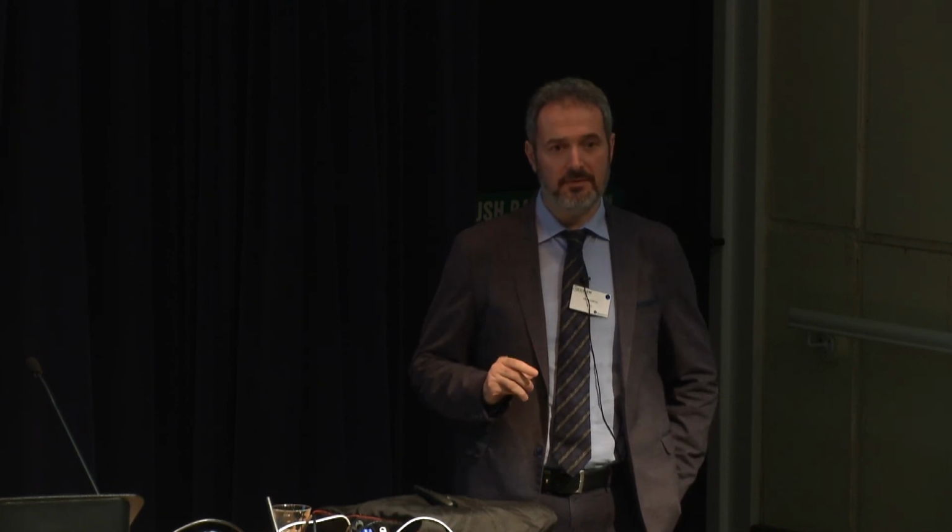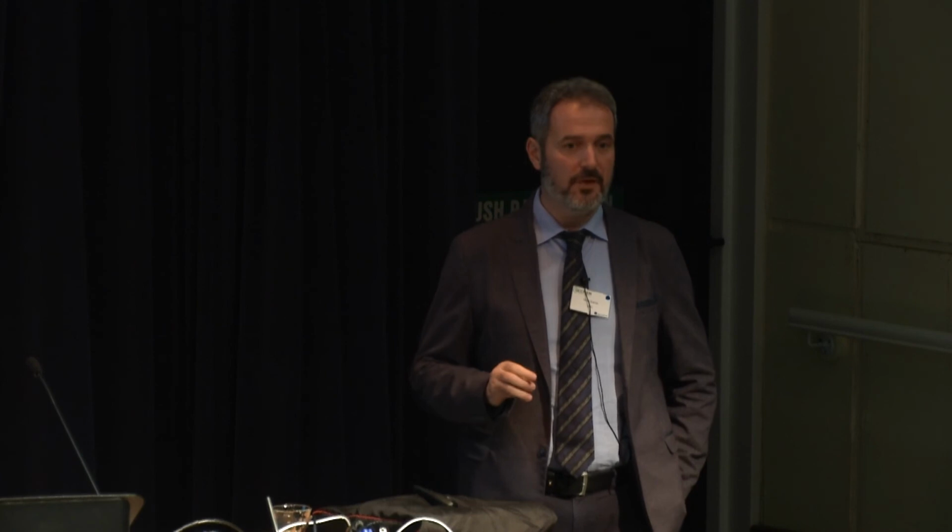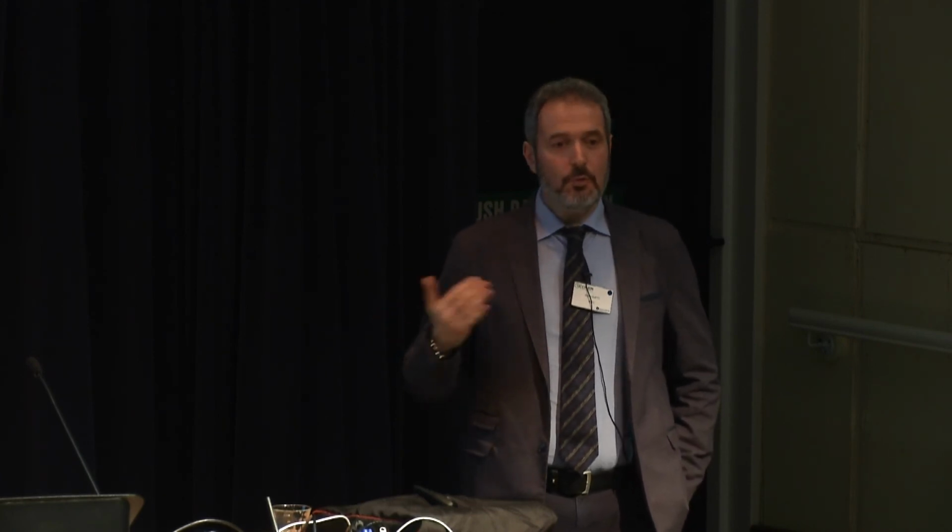Well, you can see at the moment, I think the fastest CMOS sensor in terms of frame rate is a Gatan K3 at 1,500 frames per second. If you want to go beyond that, you will start to have, I don't know, 2,000–3,000 frames per second on a sensor that has at least 16 million pixels. So it's several hundred gigapixels per second. Each pixel can correspond to roughly 12, 14, 16 bits, depending on your resolution.